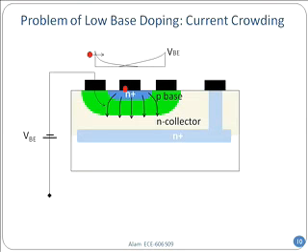You can see what I have shown is effective VBE plotted as a function of the horizontal axis within the green region. You can see as the potential, whatever you apply through your battery, a AAA battery or whatever, that's between the two black contacts. As the current is flowing in, there is gradually a potential drop, and so the VBE, the difference between them, is gradually getting smaller. And remember, it's VBE that allows electrons to be injected in the base or emitter junction. As a result, I have to be very careful about this. Only when my base doping is low, right? Then I'm getting into this trouble.